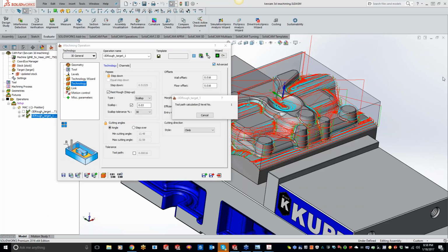Yeah, and the same goes for your CNC machine. You don't have to have this high-end, super powerful machine. Exactly. We talked about this a couple of weeks ago. This will run on your old outdated Haas mini mill or your Easy Track machine. We're getting material removed as fast as possible, but we're utilizing your machine. With the parameters of that CNC machine that we put in there, the horsepower, the max feed rate, and the RPM, we're never going to overdo your machine.